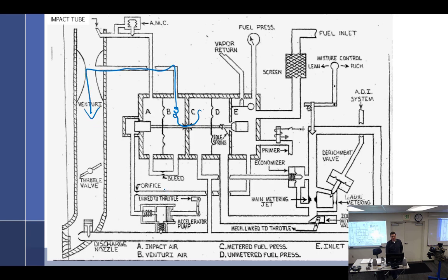We're going to look at fuel injection. I do think they swap them. They do swap them, so you'll see what happens there. So with a failed seal, it's going to run rich, only because it's going to suck extra fuel out. Otherwise, the discharge nozzle is going to compensate for the loss of leakage, so that would not be a problem.